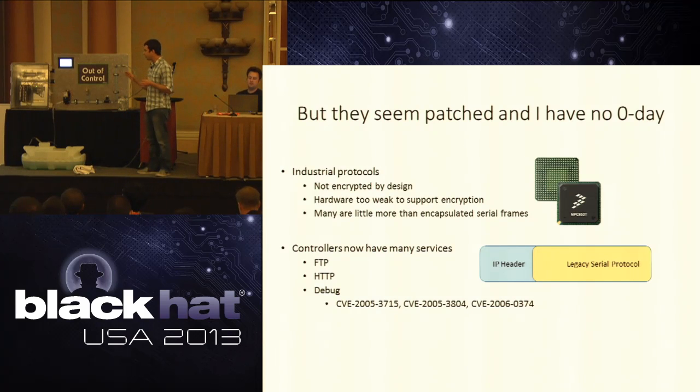Okay. So there's a couple of different things that we can do with the controller. One thing is that we can actually do binary exploitation of it, traditional buffer overflows and stuff like that, because a lot of these guys don't have the protections that you would see in a normal Windows machine, such as DEP and ASLR. These are just really old, simple machines. But what we want to do is actually go after the protocol itself. We want to build a packet to tell the controller to drive its I/O without actually modifying the logic, just telling the logic to essentially be quiet and drive those signals ourselves.